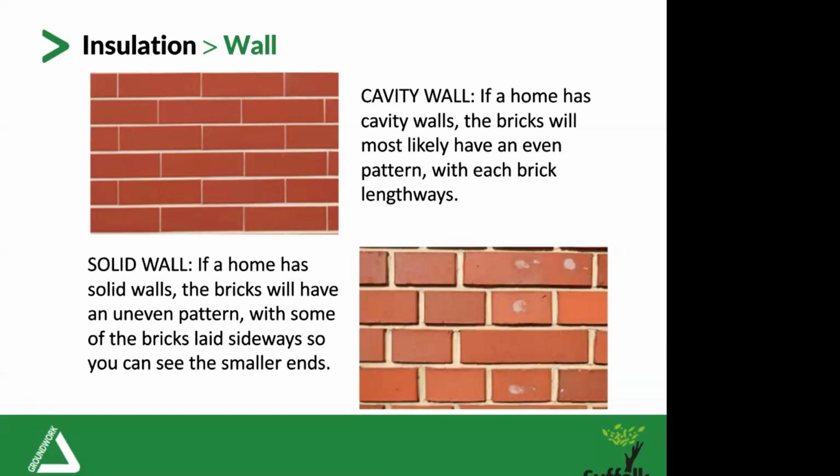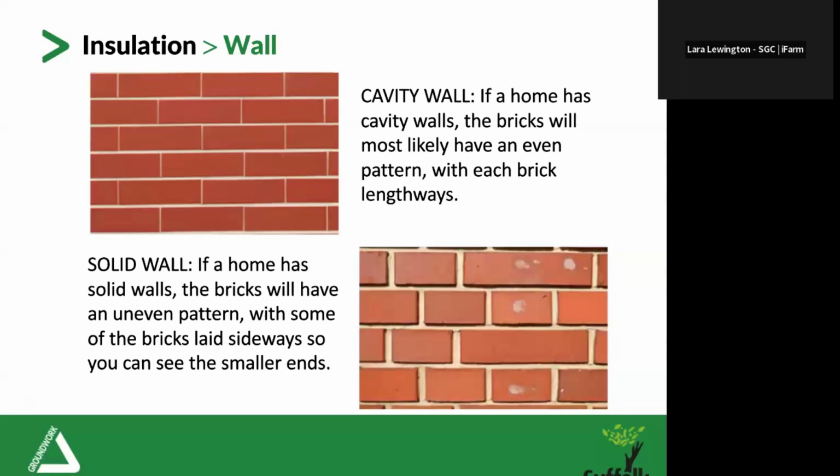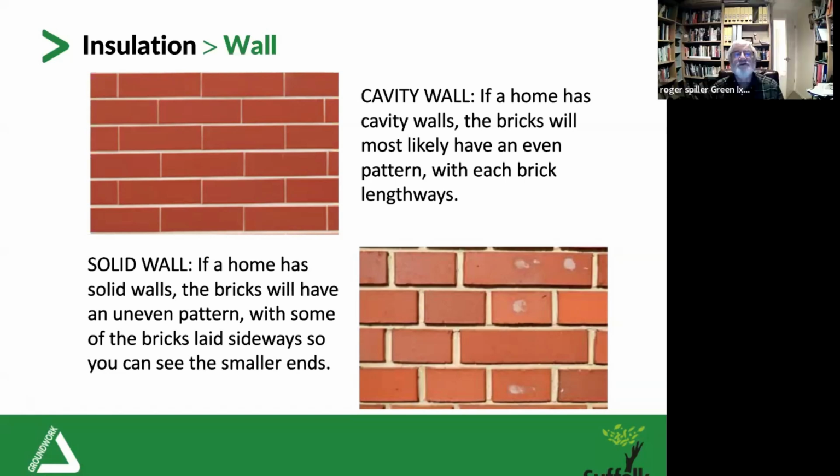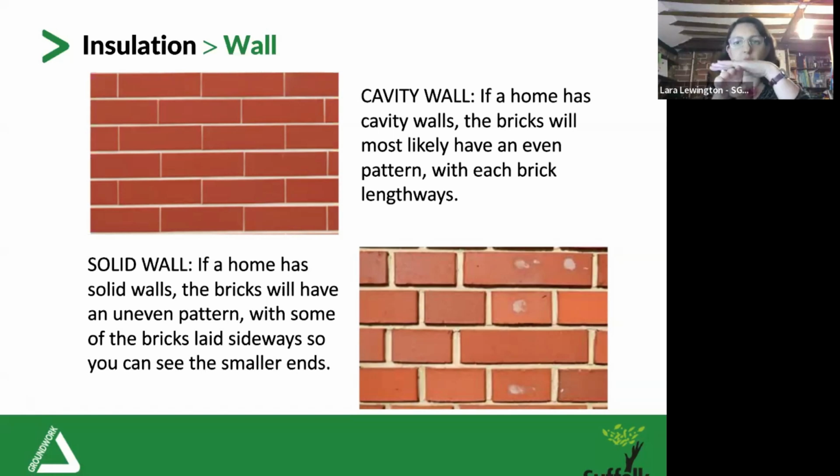Regarding the cavity wall holes that are a giveaway if the cavity has been filled since it was built: while I was doing my training to become a domestic energy assessor to do energy performance certificates, I was told that if we look at the outside wall, and it's best to see this in daylight of course, the drill holes are actually in the corners, the T corners, usually on the same row, maybe a couple of metres apart, and also in the same row vertically, rather than drilling through the middle of a brick and quite close to each other.